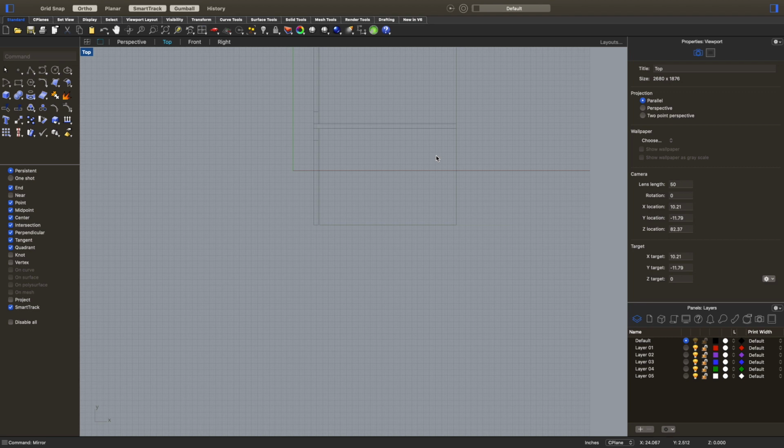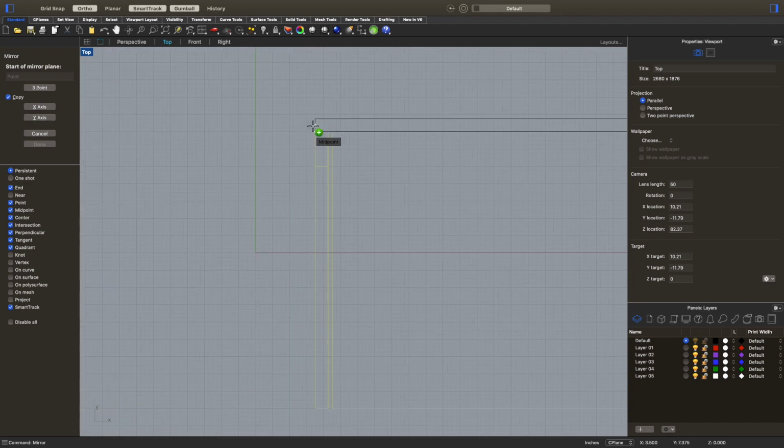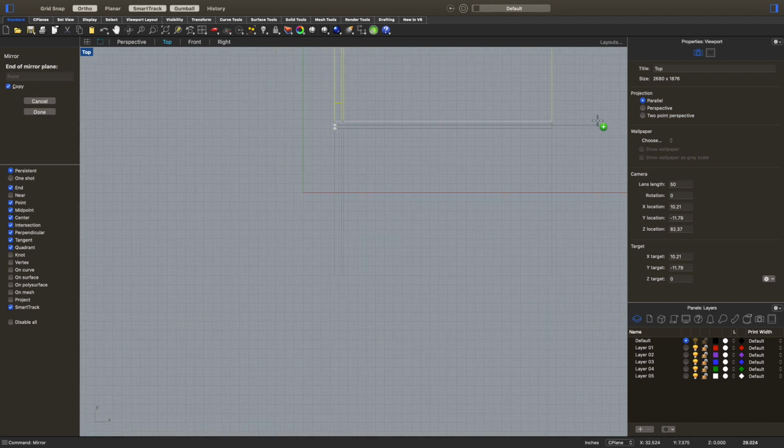Let me do that again. For the mirror command, you type the word mirror, then select the objects you want to mirror, which are the 3 rectangles on this side. You hit enter to execute, and then you draw a line in the middle that you want it to flip over. I'm going to find my midpoint, which of course I've got my snap on, or if you're on PC, you've got a snap down here. Midpoint, and draw the line this way.